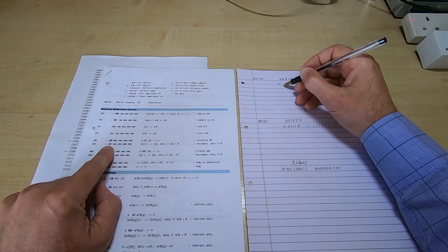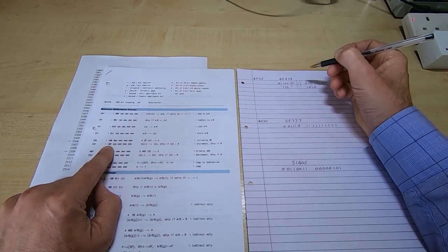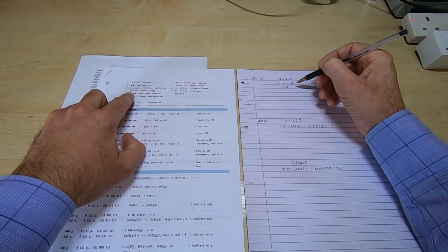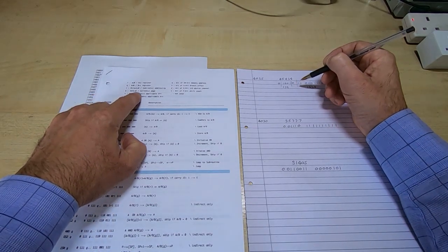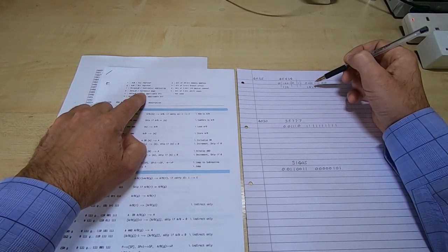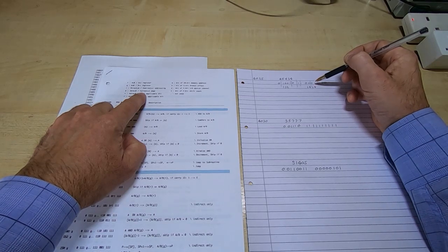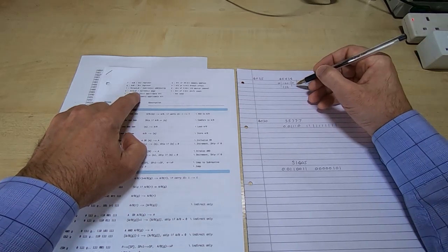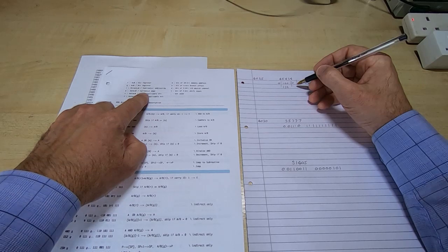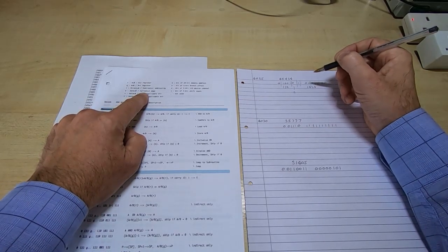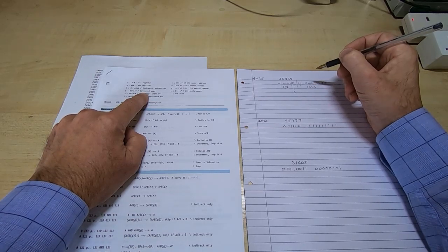The P, that's this digit, if we look at the code for that, determines which particular page we're going to jump to or from, and that's where the address may or may not be used depending on whether it's a direct or indirect address jump. So in this case we've got a 0, so 0 is current page. So in other words, we don't need to jump to a completely different bank of memory, we can stick within the one that we're currently in.